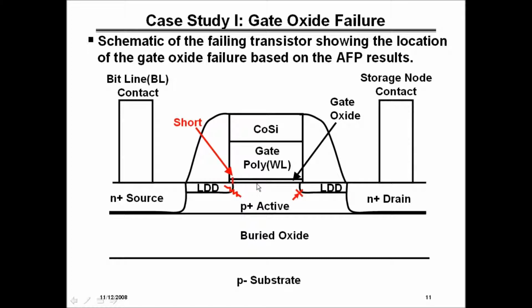With the gate oxide failure, you see this diode here, as well as when you sweep the source to the drain, you also see the diode, and so it's the difference in the electrical signatures that you get. You just see the resistor short here. You don't see these diodes when you have a resistor short that's outside, not through the gate oxide, and that's the difference.